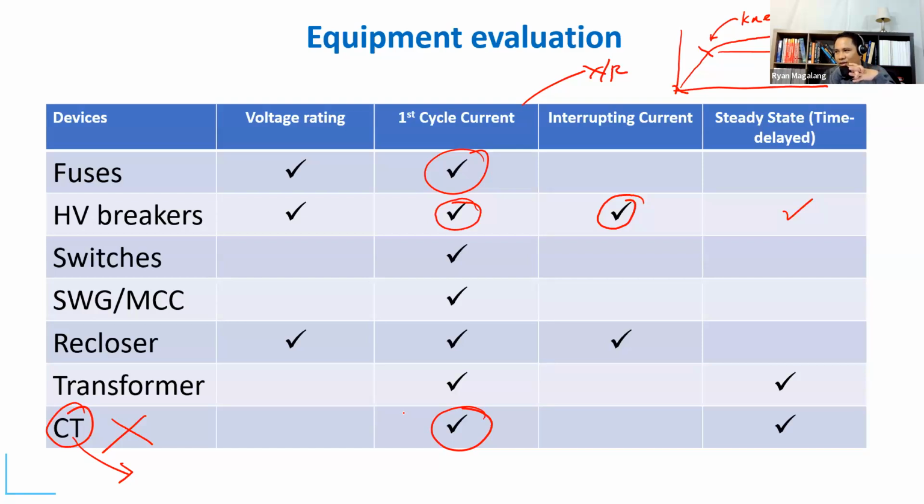So the main thing that will influence your fault current there is the utility, in that case. If the utility increases the size of the transformer serving that facility, or increases the size of the substation, then that's really the thing that would make a huge impact.